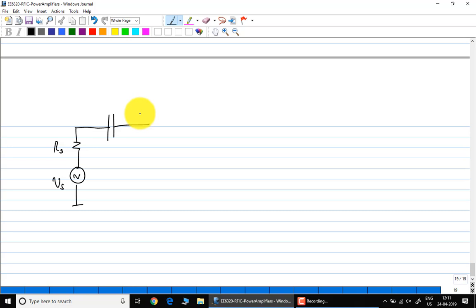So imagine you put out a wireless router in the corner of the hall, in the corner of the roof, right? You basically have three reflective surfaces right next to it. What do you think is going to happen? The antenna is going to try to put out stuff. It's going to hit the wall and come back, right? It's a significant amount of power. What is going to happen to that? It's going to travel along your transmission line, go to the input or output of the PA. If it is not matched, it will again get reflected back, get radiated. It will cause a whole amount of issues, both for the PA as well as for the transmitted signal. Okay?